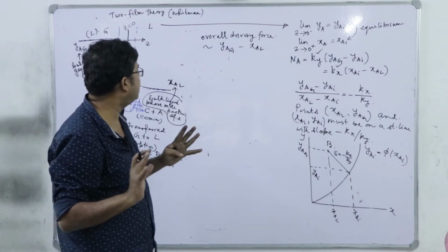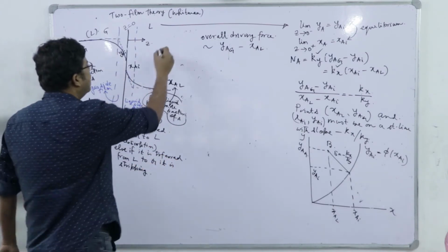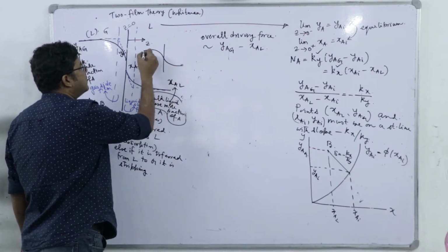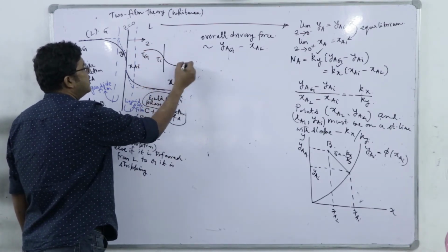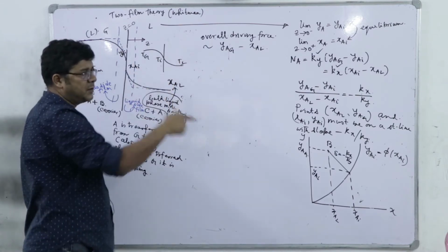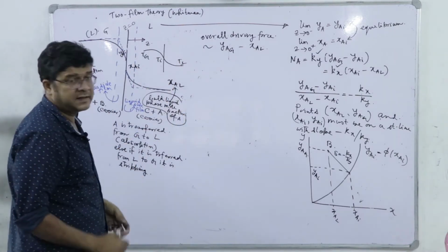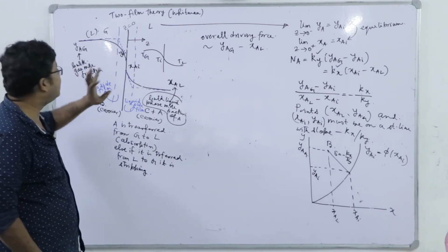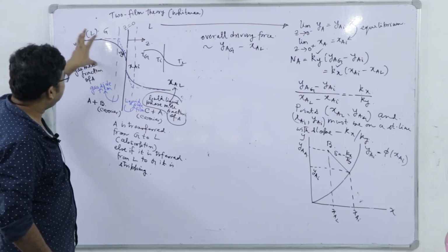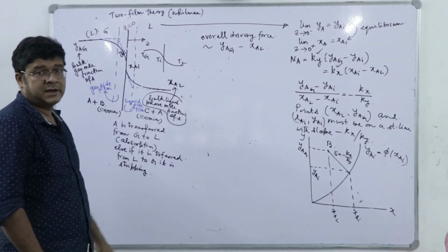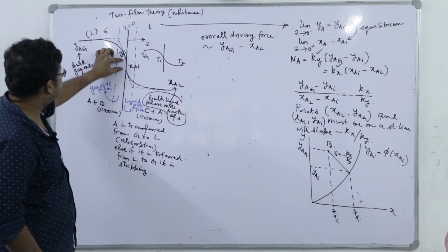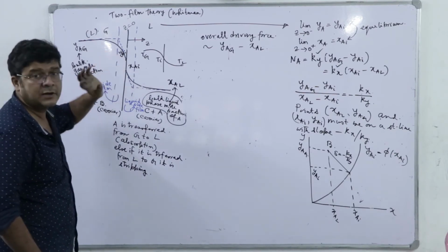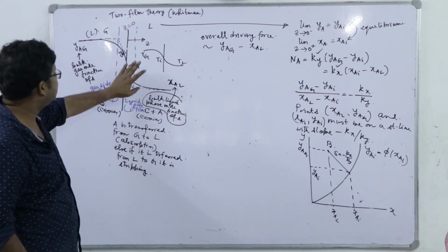In heat transfer, we do not have to think about the basis, because if this is Tg, this is Ti, this is TL, at the interface the profile is continuous. Here the profile is discontinuous. So, we have to define the overall driving force either with respect to the gas phase or with respect to the liquid phase. Here we have a discontinuity because of equilibrium; Y and X are not of the same basis.